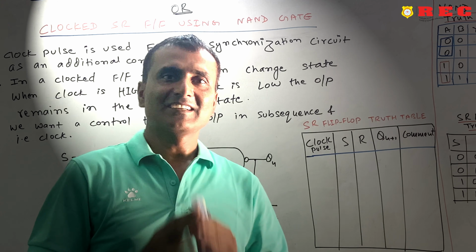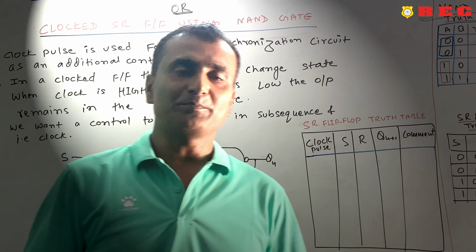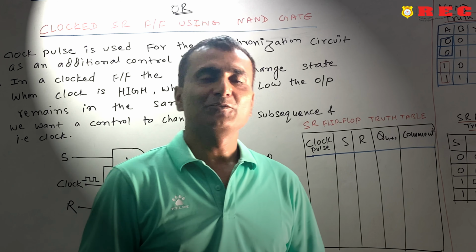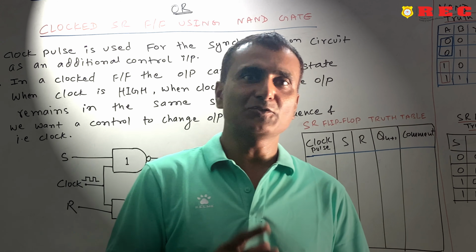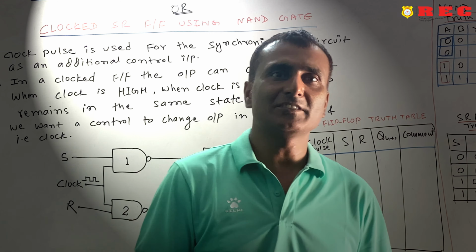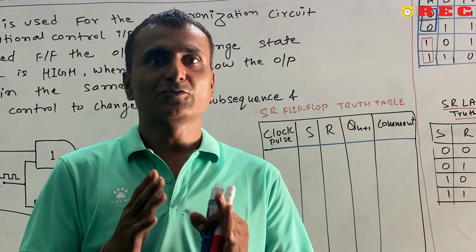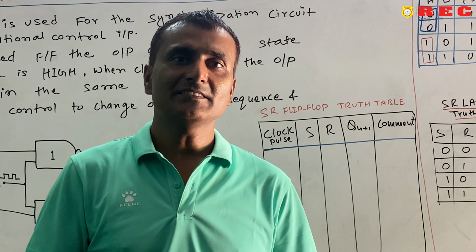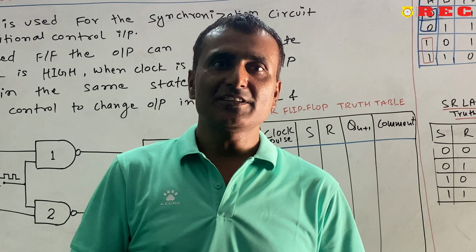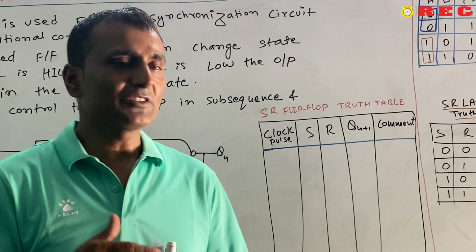Namaste, good morning. New topic, that is SR flip-flop. In the last lecture we studied latch, what is latch and what is flip-flop. You might know the little bit difference between latch and flip-flop. Latch is without clock pulse and flip-flop is with clock pulse. So, we have studied latch using NOR gate and latch using NAND gate, and today we are going to see the SR flip-flop, means the latch with clock pulse.